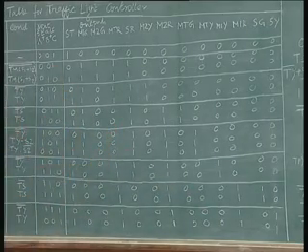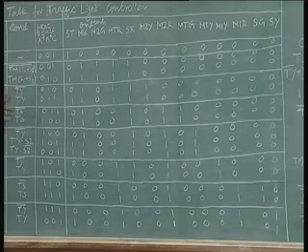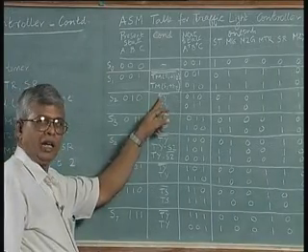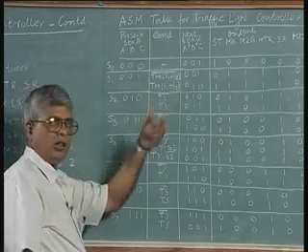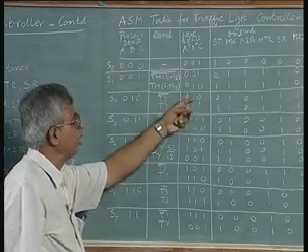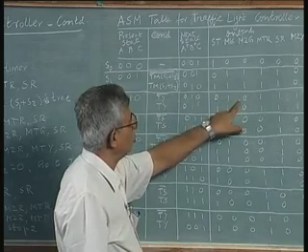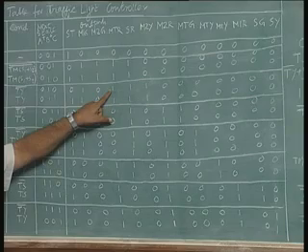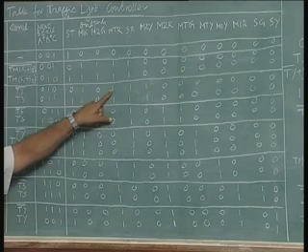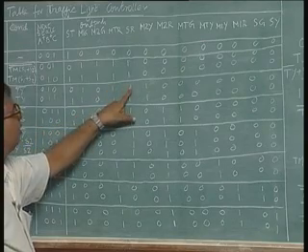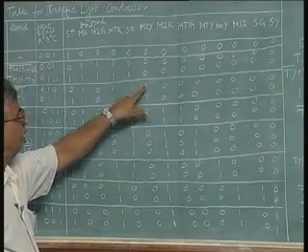So as corresponding to the state of 0 1 0, you are waiting for the yellow time to be over. As long as the yellow time is not over, you continue in the same state, keeping the main 1 green, main turn red, side red, M2 is in yellow state, all others are zeros.